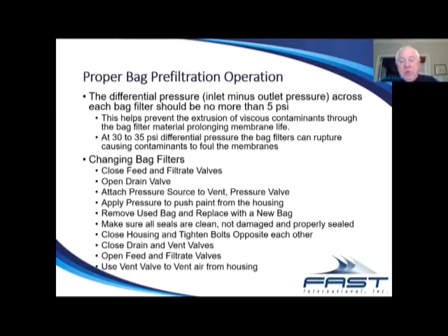The other thing to warn about, if you don't take particular care, is that these bag filters will rupture at around 30 to 35 psi. Typically, if you're operating at 5, you don't have to worry about that. But we've seen instances where people have, for example, power washed their tanks, and then smartly they say, well, put it through the bag filter, but not the ultrafilter. And if they're not careful, those bag filters will build up differential pressure very quickly and rupture, and then it goes through the bag easily.